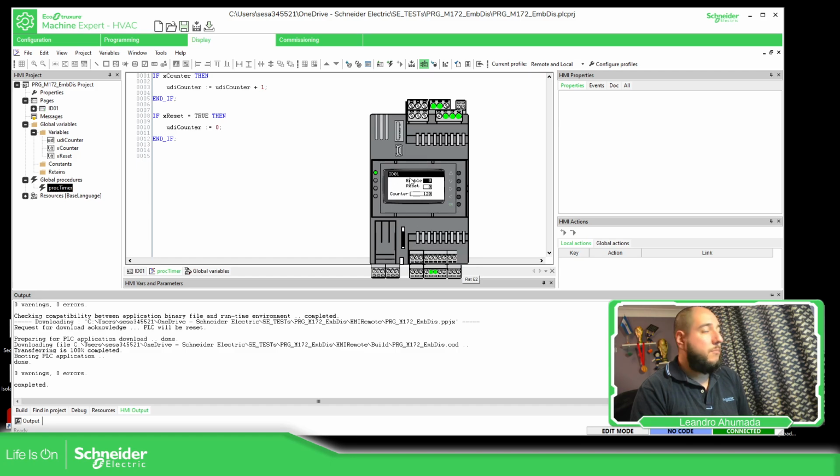One thing you can do in order to change the page is to activate a counter on the global OnTimer that counts to 60 to have a loading bar, and then when it reaches the value that you want, jump to another screen. In order to jump to another screen, there is an event or function that you need to know: send event, and you need to activate a virtual key. But I'm going to explain that later.